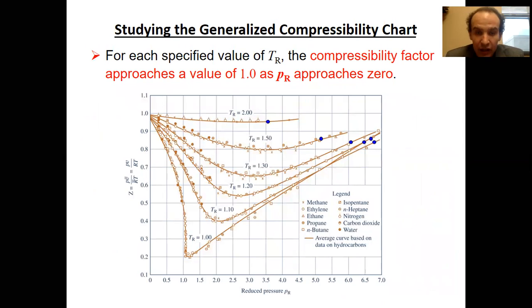So basically here it is. And also we recall last time that of course when reduced pressure tends to 0, then you tend to ideal gas. But otherwise it's not the case. And you may see that in fact what this diagram shows is the competition between sensible and latent energy. You understand somehow pressure is latent energy. It's interaction, right? One particle doesn't have pressure. Temperature is sensible energy. So what I see at the first plot here, I see that my reduced temperature is 2.0. What does it mean? It means that sensible energy here dominates over pressure. It's high temperature. So I have ideal gas in all the cases.